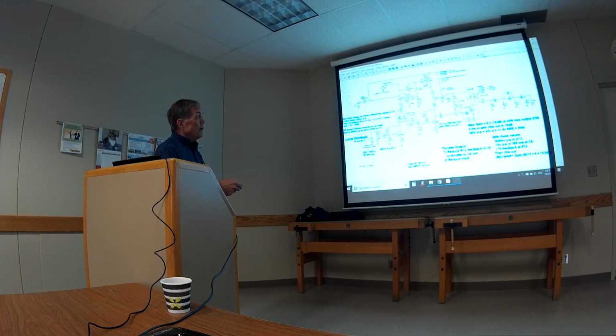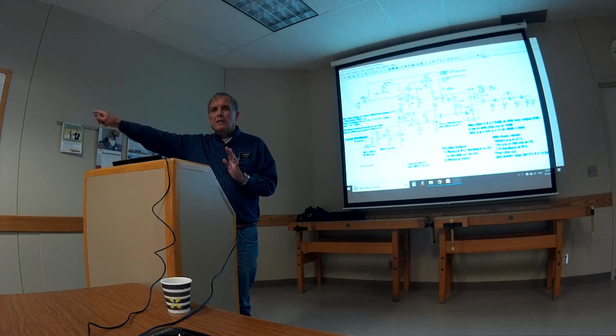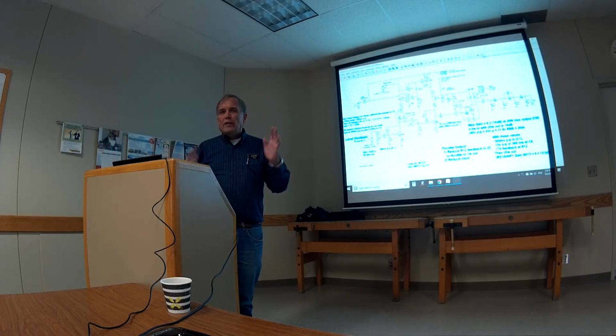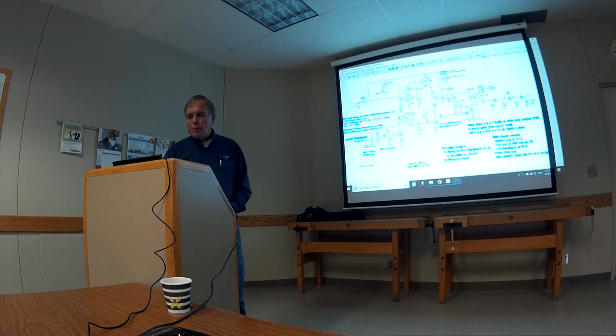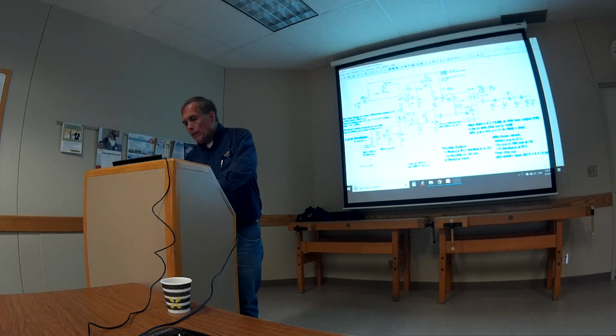The power amplifier is getting shut off with the key as well as an early stage, because sometimes an early stage has enough power to actually sneak out the antenna. They call it back wave. And this will shut that off too, so you don't have any output at all coming out of it. And rather than run this model, I'm just going to show you what the output of it looks like.